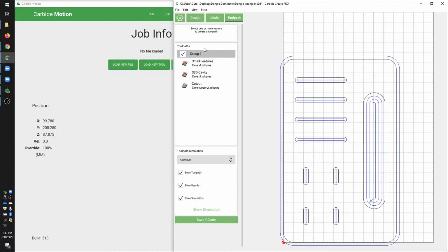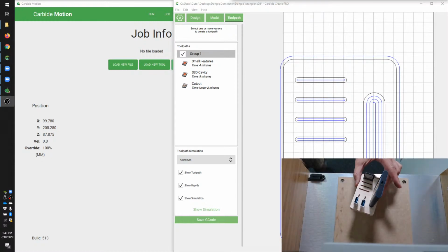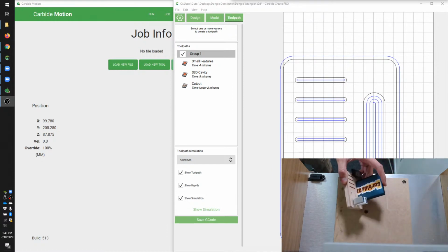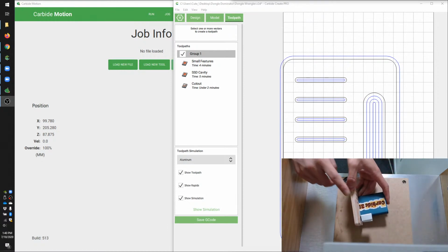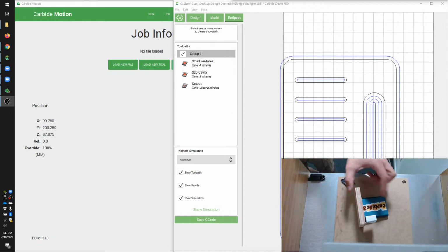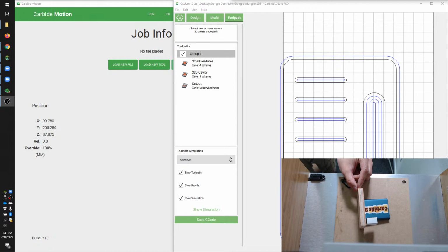There's also one more little nuance of the part that I realized. So let me bring in... So this is supposed to be 1/2 inch plywood. Realistically, it's about a 32nd of an inch less than that. So when I programmed this stock in as 1/2 inch thick, and I told the end mill to plunge as deep as the 1/16 inch cutter could go, which is a 1/4 inch, it actually effectively only plunged to maybe 3/16, a little more.